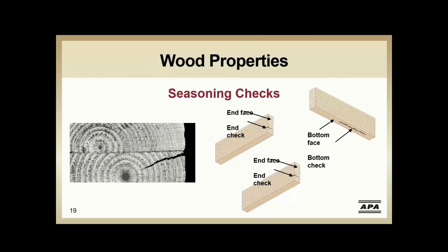As we think about how wood reacts to moisture, first wood swells and then it shrinks; it gains and loses moisture in response to the changing relative humidity, and to a far lesser degree, temperature can impact it as well. If the difference in the moisture level between the core and the surface of the wood becomes great enough, the internal stresses associated with these dimension changes can induce tensile stresses perpendicular to grain. These stresses can result in seasoning checks developing across the annual growth rings. It's common in solid sawn lumber beams. But as I said, checks should not be confused with delamination.